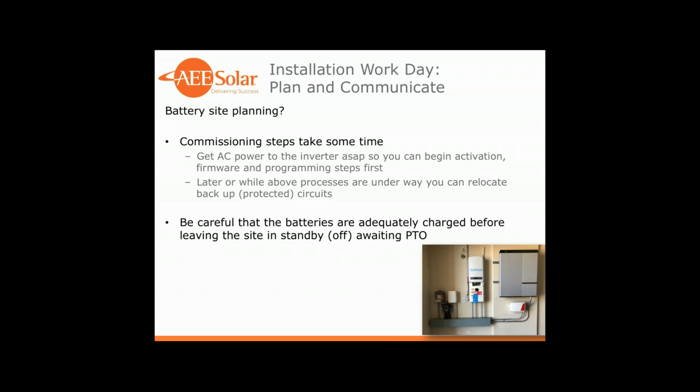So if you want to be a really professional team, what you want to do is get the AC power connected and on to that inverter as soon as possible. That way you can get those slightly longer or more tedious steps running. You can get the firmware going, some of the programming, the activation, and those details. And while you have those steps running, you step aside and start working on the backup or protected load circuits.